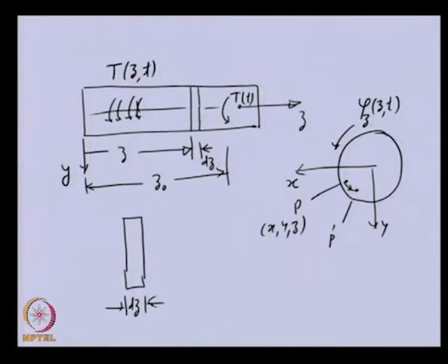and once we have taken it out from the shaft, the reaction torques will be acting on both sides of this particular plane. So, let us say in this particular direction the torque Tz is acting, which is reactive torque, coming from the other end of the shaft, and because the inertia property is continuously changing, we expect that the torque will change at the other plane, and this will be given by this expression.